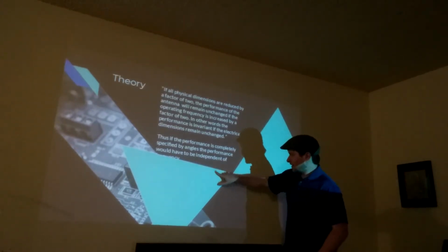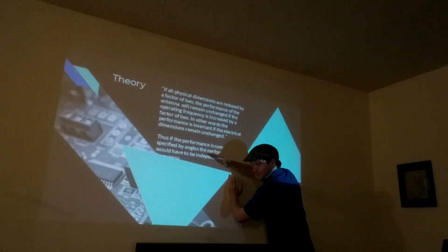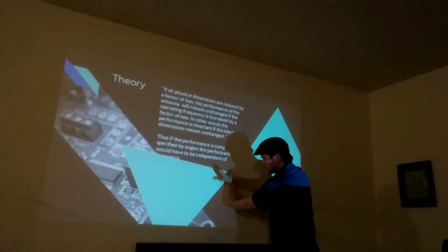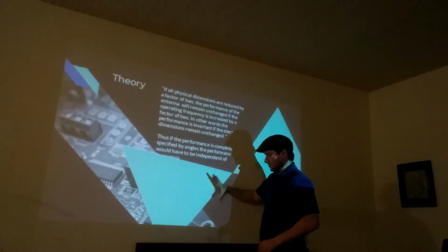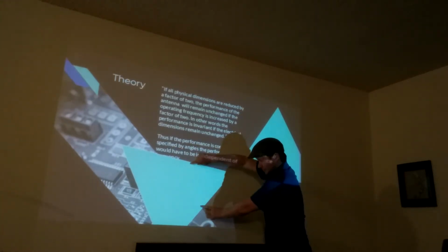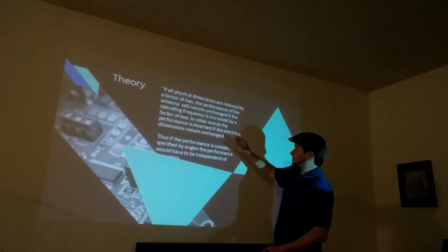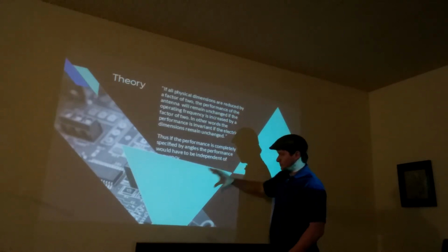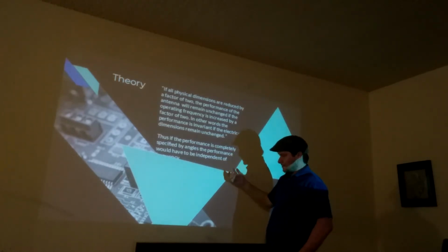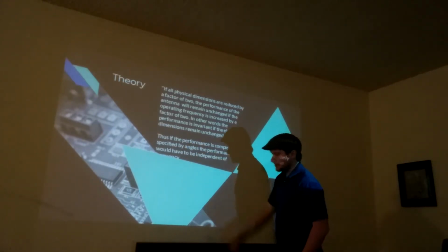So this is half the wavelength right here. If you were to increase the angle, you would be increasing the operating frequency of this antenna. Similarly, you can scale this antenna, which would also make this length longer, such that you would have a higher operating frequency. So by scaling or reducing the physical dimensions by 2, you are increasing the frequency by 2, since the wavelength of higher frequencies is smaller and the wavelength of lower frequencies is higher.